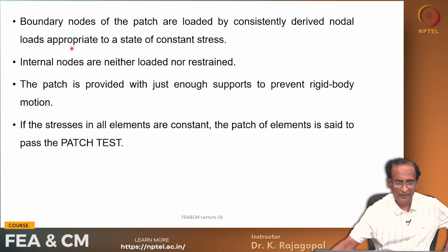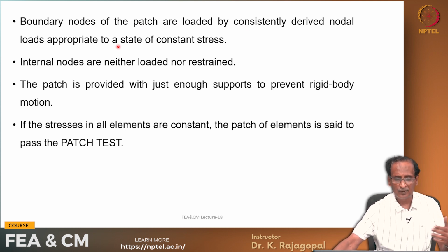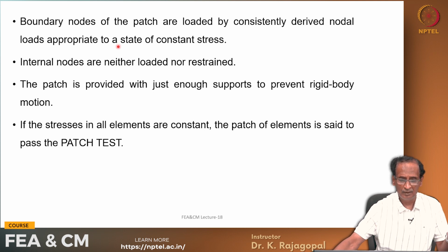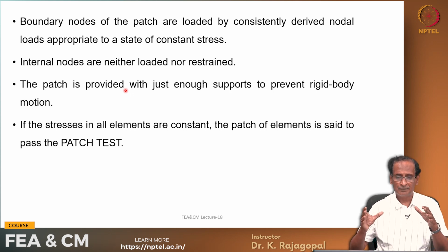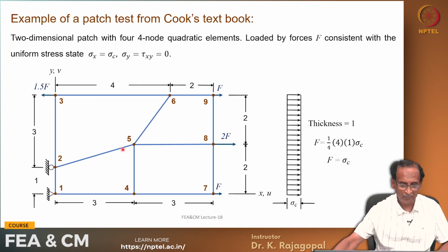And in this test, we are going to load the boundary nodes consistently, derived from our N transpose T ds calculations, and then the internal nodes are neither loaded nor restrained, and the patch needs to be provided with just enough boundary support to prevent any rigid body deformation. And that is what we have done here.